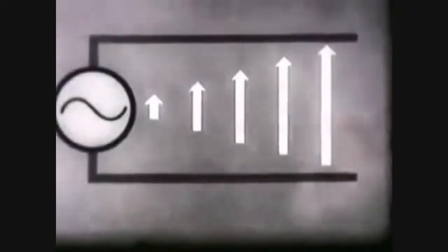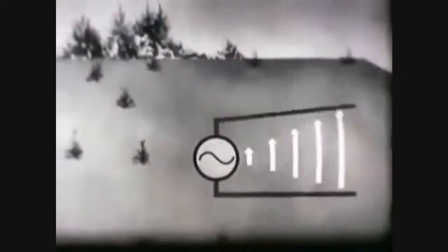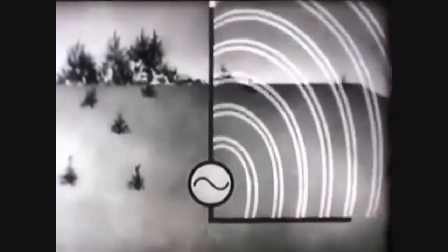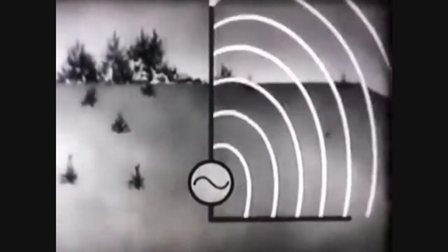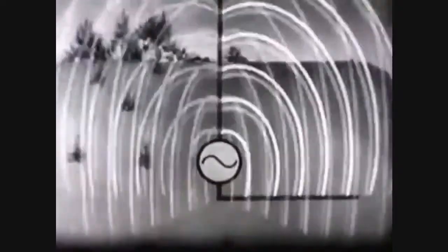What can we do about this? Well, the same quarter-wave transmission line holds a few more tricks up its insulation. When only one wire is moved perpendicular to the other, the closed electric field which existed between the upper and lower conductor becomes a partially open field. Since the lower conductor is grounded, similar electric fields occur all around the upright conductor.